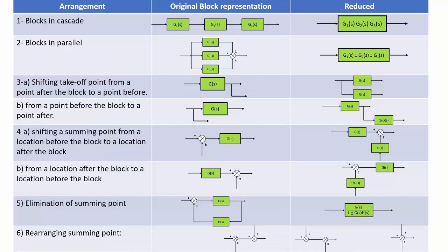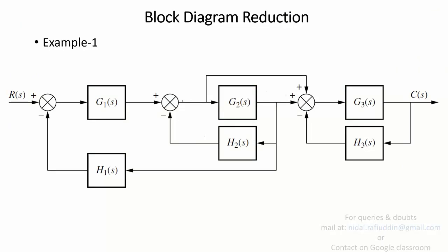All right. So starting with the first example. Let's say we're given a system represented by the following block diagram. This comprises six components which are represented by individual transfer functions G1, G2, G3, H1, H2, H3. Notice that the term H in blocks is used for feedback loops. So if you are going to have a feedback within the block representation, that is in most books represented by H. And the forward paths are represented by transfer function G.